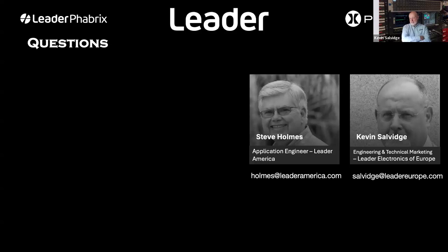Personally, I don't like it switching myself. I like to have the alarm set so that I know I'm looking at 2020 HLG, and if suddenly a 709 signal comes in, I get the warning messages that maybe somebody has routed the wrong camera feed to me, or it's not converted. You'll get the mismatch on the screen, so that you can correct it before your client rings up to say that the HDR and the SDR look very similar. Possibly it has something to do with the way it's lit.